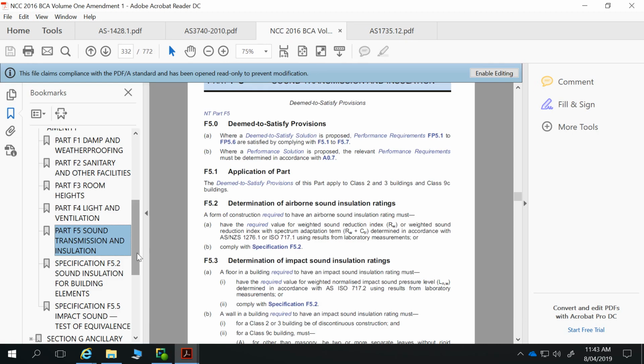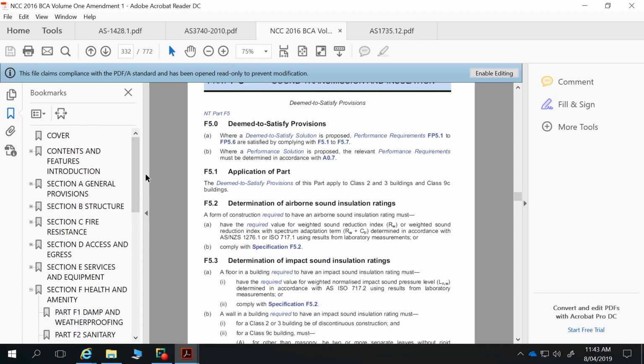Other minor details we're going to have to look at with our buildings are fall protection. It's very important, well, it's very stringent, and you probably would have covered this a little bit with stairs design. So you've got your rise and run dimensions with stairs, but then you also have to ensure that you don't have a 125mm sphere pass underneath your stairs for any open tread stairwells.